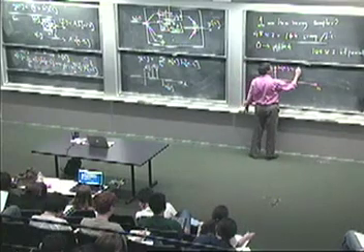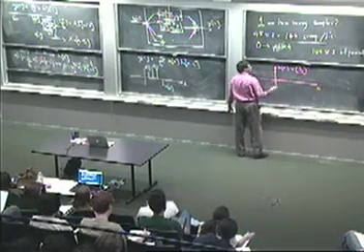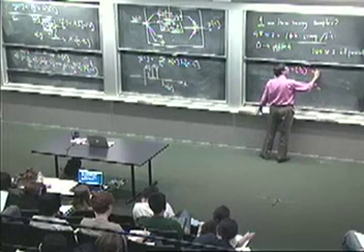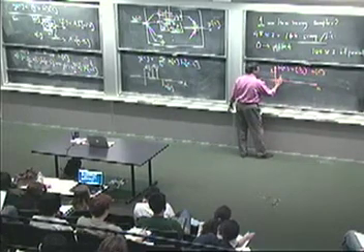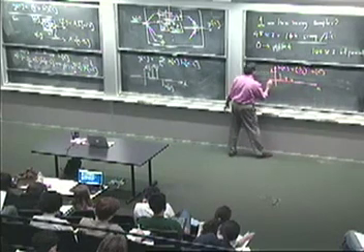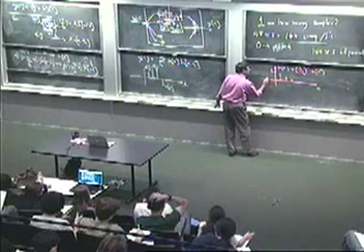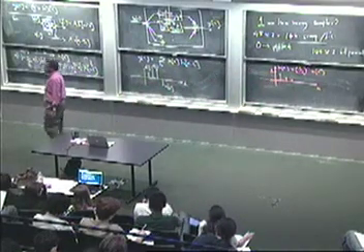Let's say that this is 1/2 to the n times u of n. So for positive time, it's kind of a decaying geometric series. And for negative time, it's 0. Okay? So that's an example of a unit sample response of a system.